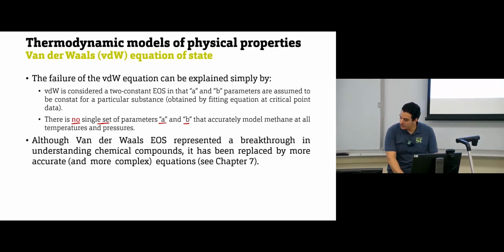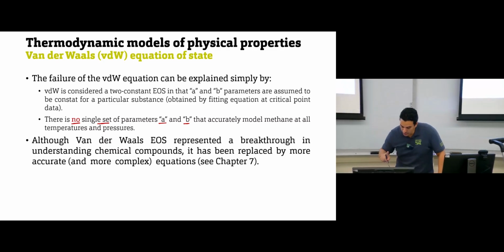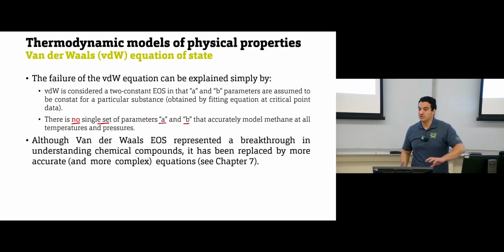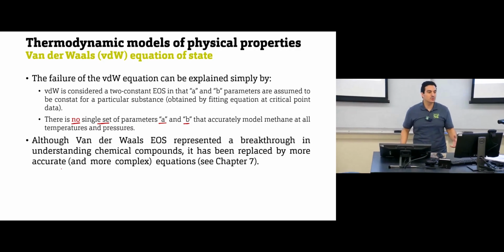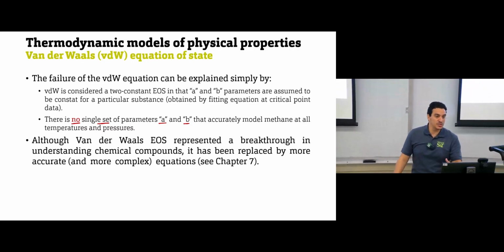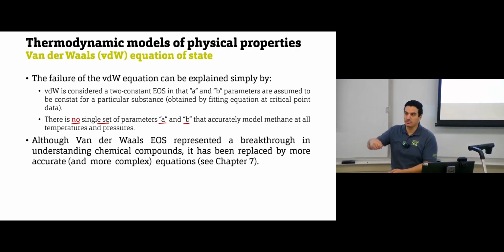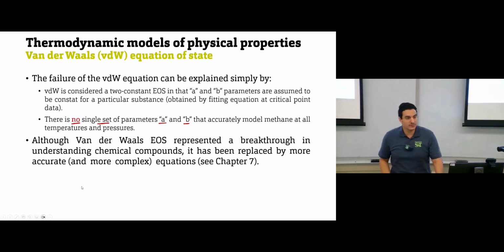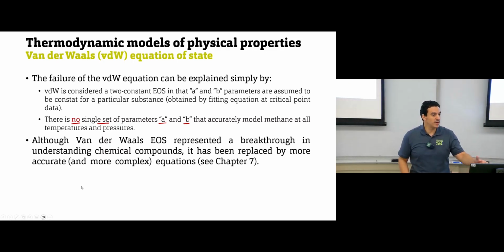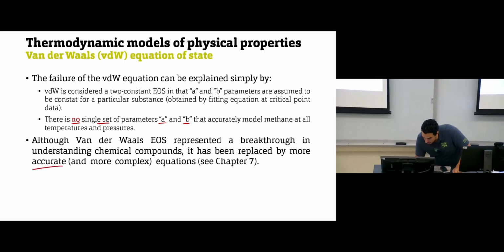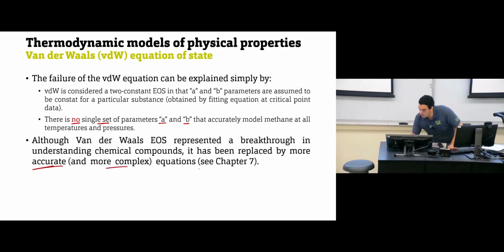No. The van der Waals equation of state is a very advanced equation. It was considered a breakthrough when van der Waals developed it. But nowadays, by the way, no one is using it. In the exam we can use it because mathematically it's simple, so we can make calculations in the exam using the van der Waals equation of state. But in real life, in simulation packages for example, when they need to use an equation of state, they don't use van der Waals. They use more accurate, more complex equations.